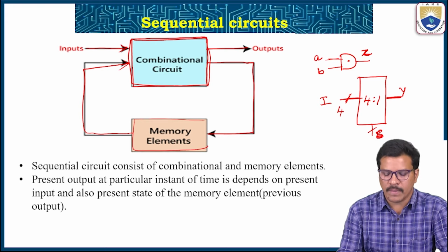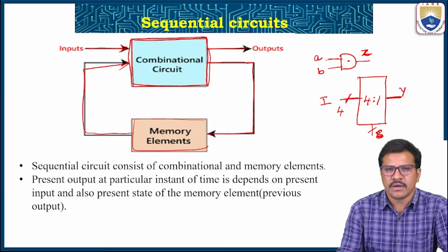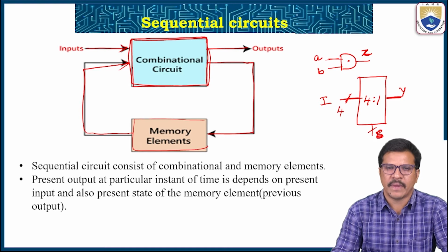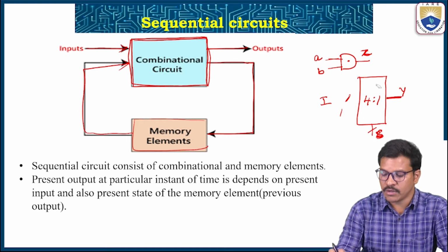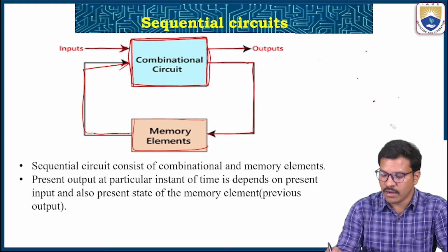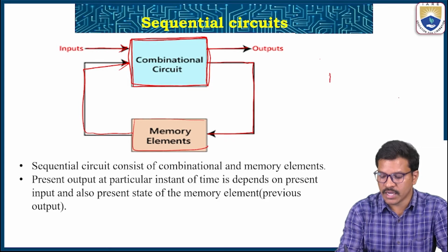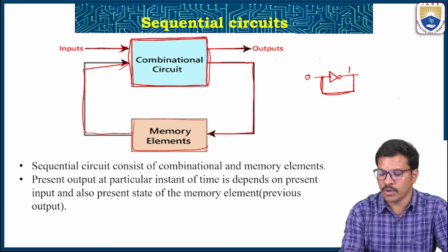When I am talking about memory elements, how can we make this memory element from digital circuits? Memory elements can store one bit of information. Right now we can make them with some kind of circuits. So what is the basic fundamental for any memory element? If you see any basic circuit, let us take an inverter. The output of the inverter is taken back to the input. If I give 0, the inverter output is 1, and that 1 is fed back to the input. So then